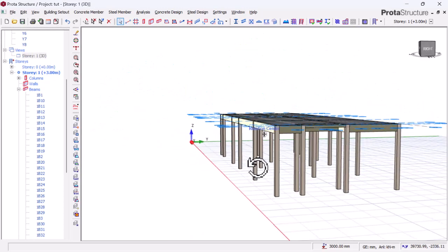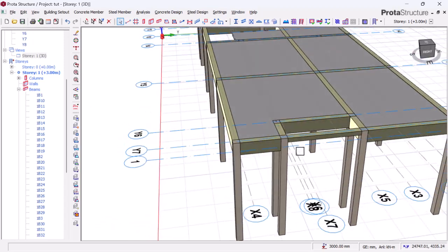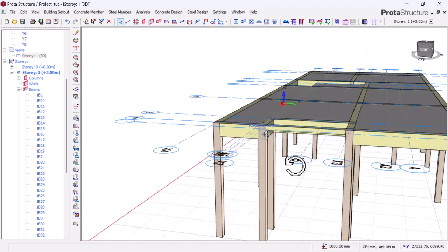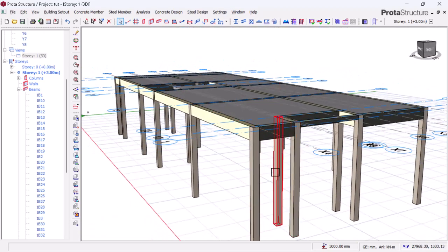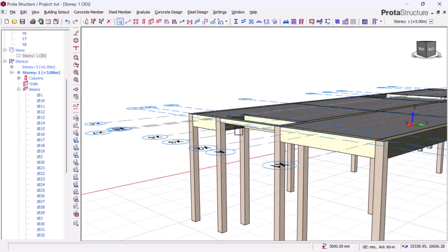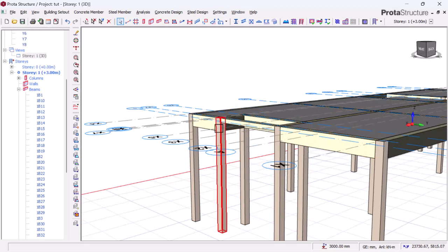You can see they are having a smaller shape beam so that when we insert our slab, it's going to take a uniform area at that area. Don't forget that this is a wall area. This is where we have our block wall. So by the time this block wall is laid, this area will be covered. So the same thing here. If you're going to introduce this same depth of beam here, somehow it might look ugly. So it is very much preferred for you to keep it this simple.